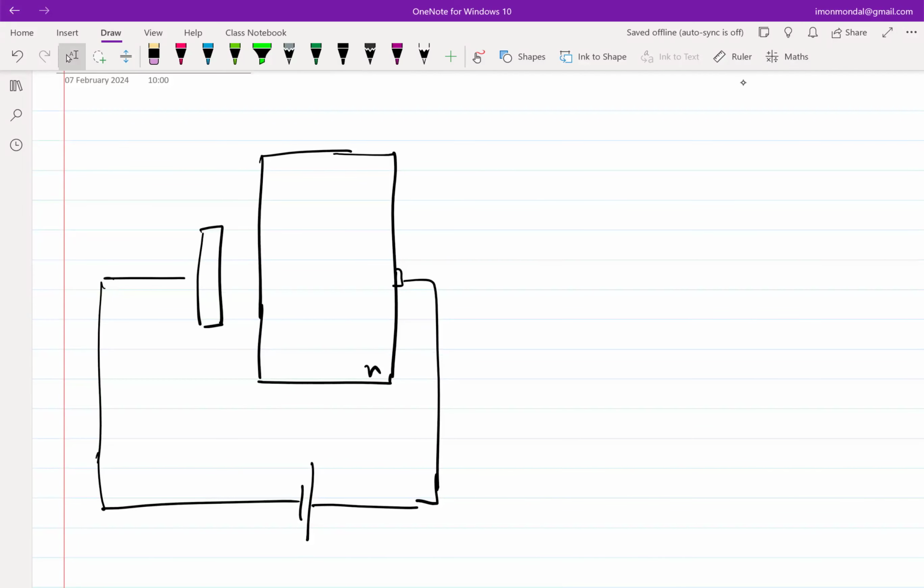And then we also say that here you have, let's say, P plus, make some P plus contacts. It's almost like a well or a tub where you have generated an island of holes, kind of, right? And then we further say that all these PN junctions, now this is a PN junction, this is a PN junction, we must ensure that they are reverse biased, because at the end of the day, we want the channel to be formed here.